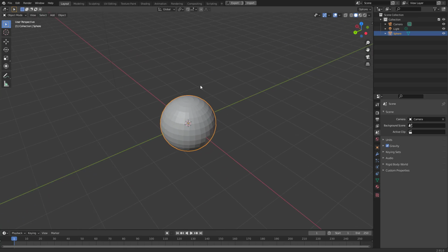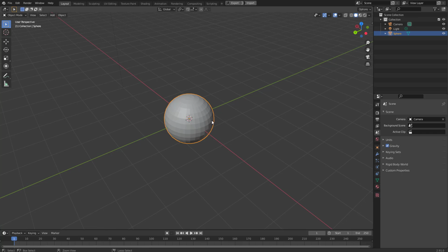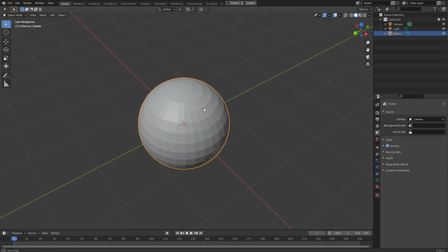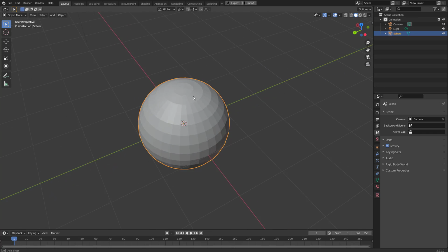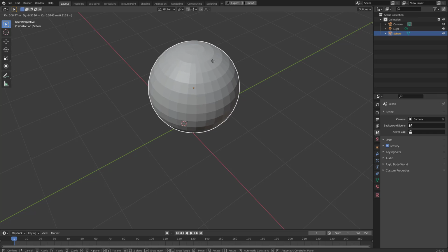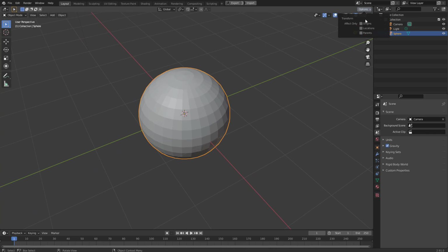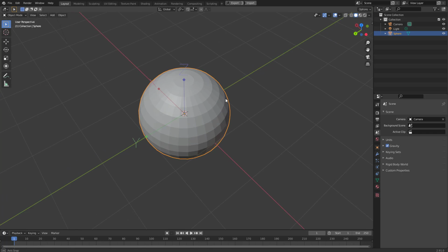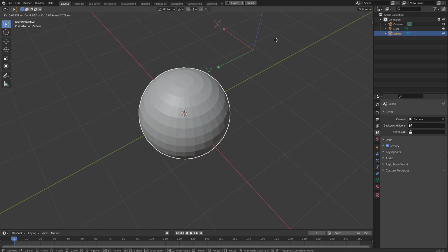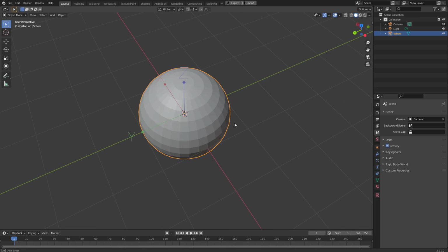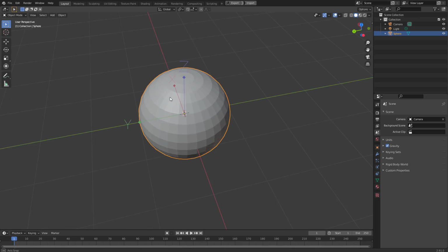So in some sense, you feel the advantages, you feel the disadvantages compared to Maya, for example. Like one of the huge disadvantages: how do I move the origin? The only way I know that's faster is to go to options and turn on affect only origin, and then you can start moving the origin like that. But in Maya, just hold down D and click anywhere, and it snaps the origin there. Now this wouldn't be that easy.